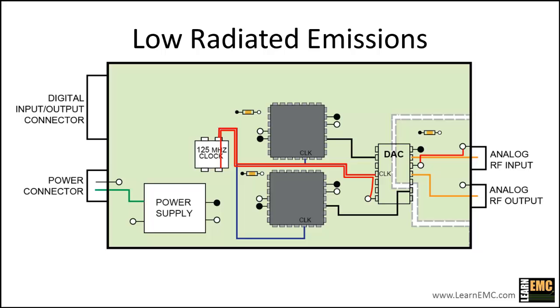In well-designed printed circuit boards, the return current for RF signals always flows in a way that minimizes the current loop area. So there's very little likelihood of any significant amount of digital current sharing copper with the analog RF current. This means putting that gap in the ground plane did not do anything to help protect the analog signals, but it did set up a situation that's likely to lead to a radiated emissions problem.